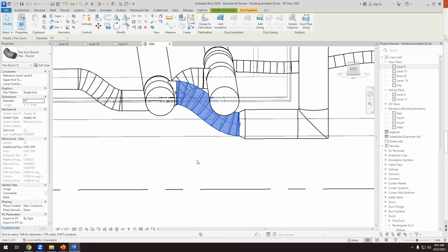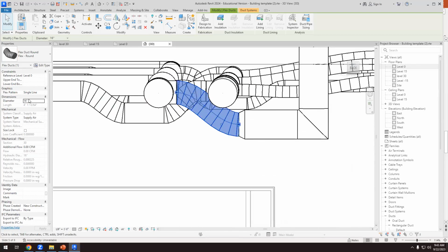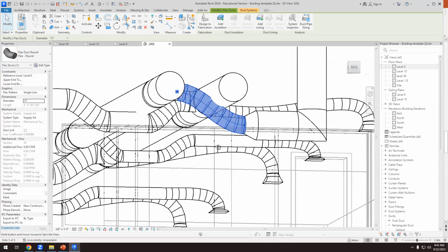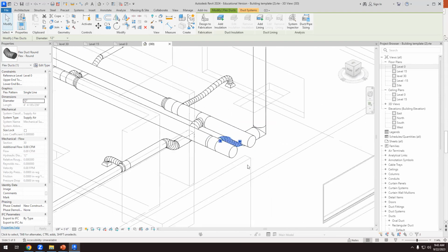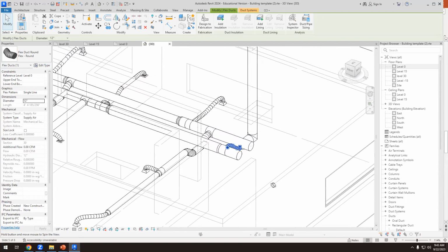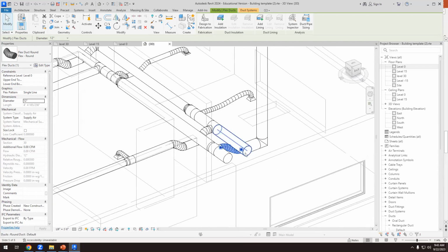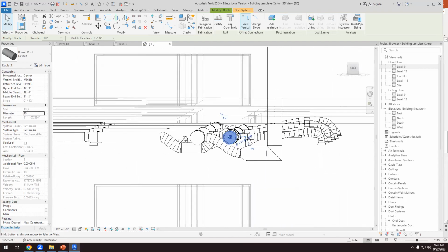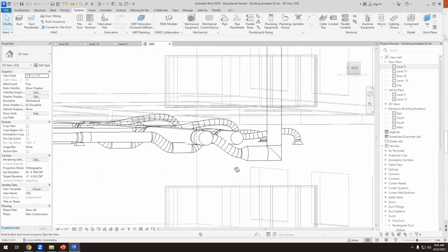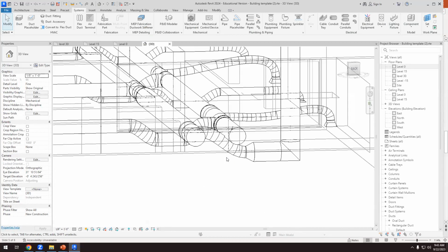I mean, there are different options here. I'm doing something because I'm tired and I'm reducing the size of this flex duct to 12. And even with 12, it has this. Okay, but I think I have good. No, I don't have good news. Maybe I can reduce this one a little. It's 20. I'm going to make it 18. Okay, I think now it's working well.